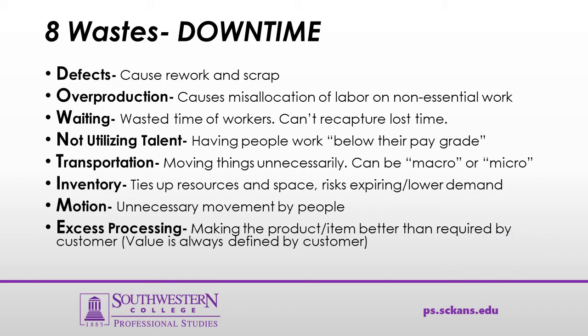So when we look at waste, there are essentially 8 wastes, and this is probably the central tool of lean. If you're interested in learning about lean, learn PDCA and learn the 8 wastes, and you'll have a very good foundational level of information. But the 8 wastes that are commonly seen would be defects, obviously because of the rework that it causes, overproduction.